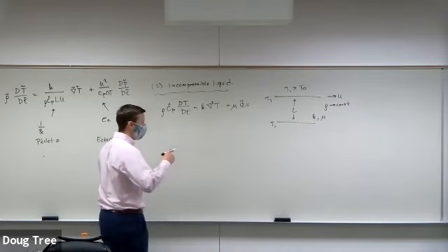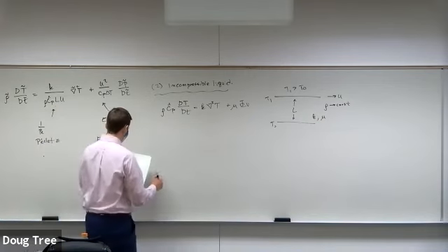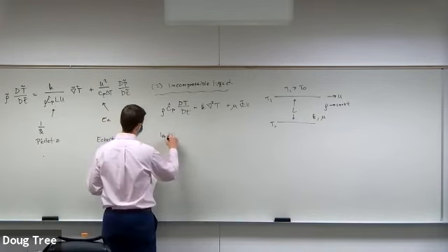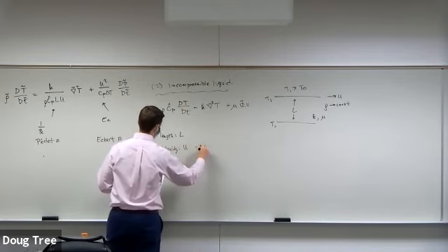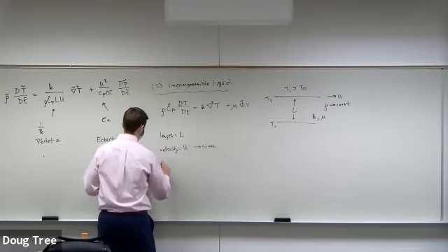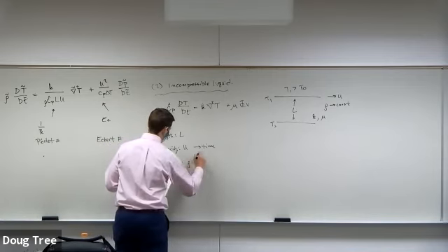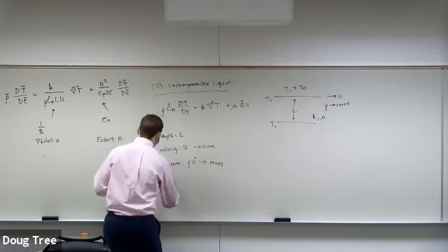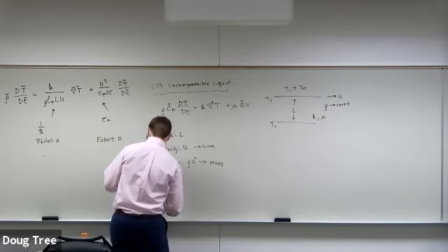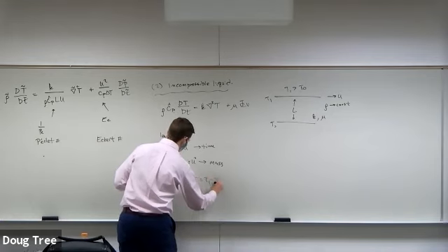So we can think now, what are the fundamental dimensions? They're all the same things I wrote over there. The length is L. The velocity is u, which gives us time. The pressure is rho u squared, which gives us a mass as well. And the temperature is delta T, which is T1 minus T0.